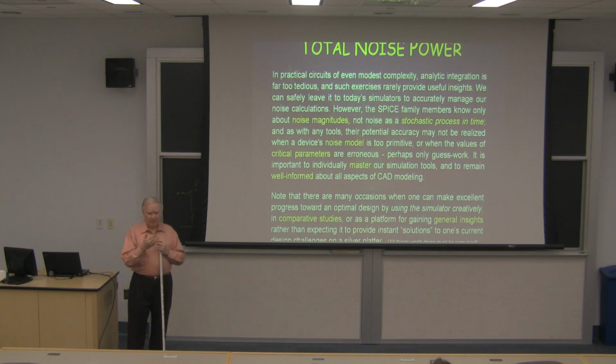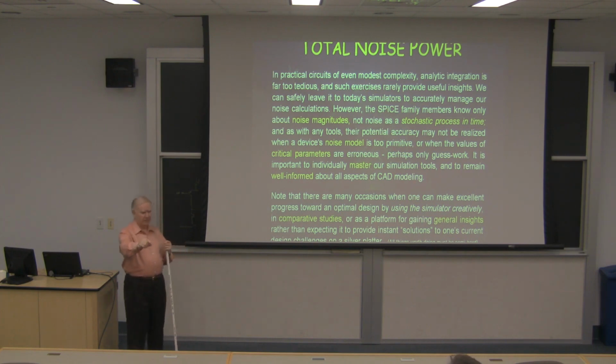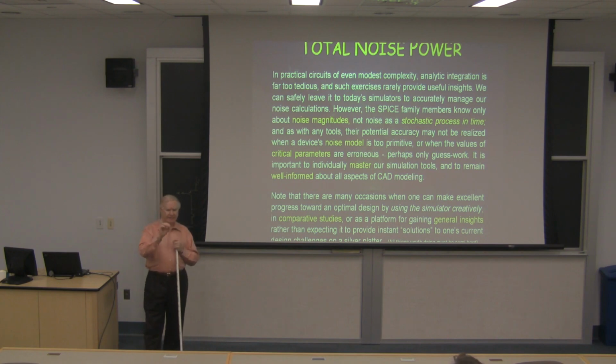And our own simulator, which is called ADICE, incorporates something I call TNT, which stands for Transient Noise Test. That is to say, when we do a transient analysis, we stop at every point where the matrix has been solved and we've reached equilibrium at that particular time point, jump out of that process into the noise process, measure the noise at that instant at some specified frequency, and then pop back into the transient analysis, go to the next time point, and so on. So what you end up with now is a vector which is noise versus time. And I'll show an example of that in a bit.